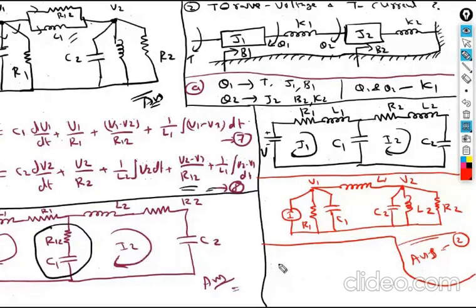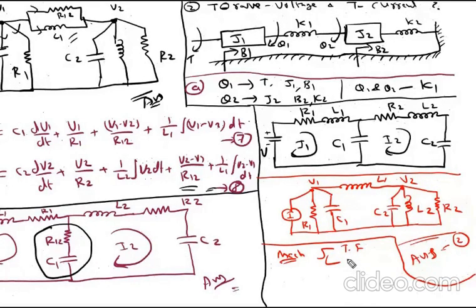Now here, as a part of this mechanical system, the overall conclusion is, in two ways he will be asking you. One is to determine the transfer function, and another one is he will be asking you to obtain the electrical circuit. How to find out the transfer function, everything we have discussed in the previous classes. Now in this class, we have discussed how to find out the electrical circuit for the given mechanical system. For this given mechanical system, as usual, first extract the data related to all the displacements. Maximum number of nodes you will be getting is only 2 based upon the data from the previous question papers.